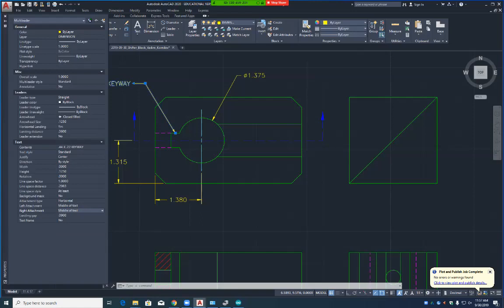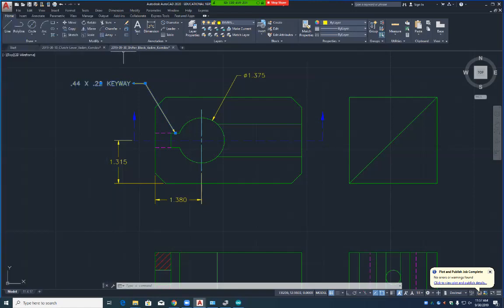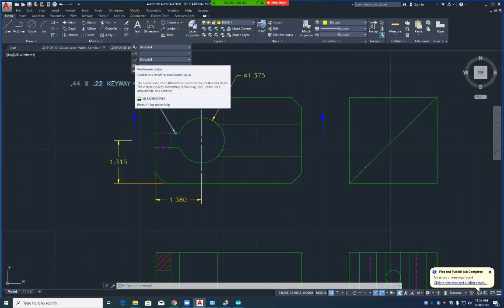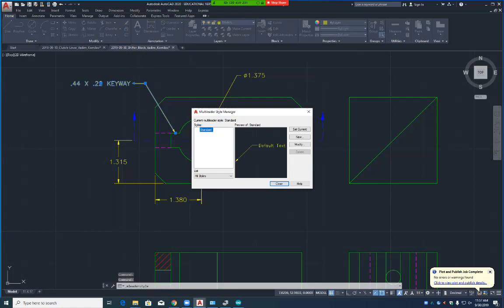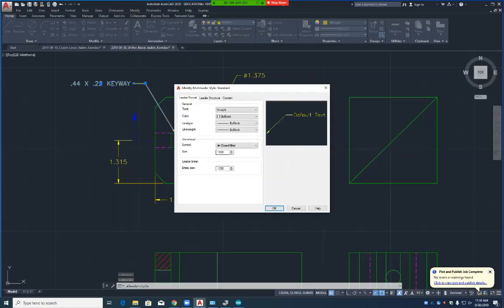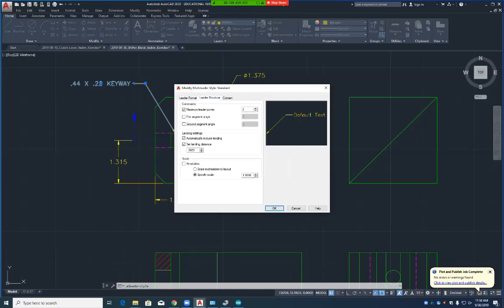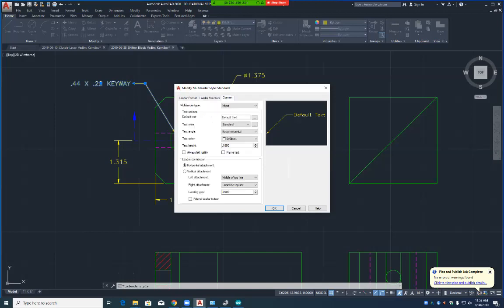Okay. Now the very first box is your text style, dimension style. What's the third one? Multi-leader style. This is a leader we're putting on, isn't it? So I want you to go into that multi-leader style right here. Now, doesn't this look very similar to your dimension style? Yeah. So what do I do? Modify. Okay, now we only have 3 tabs instead of 7 tabs, right?